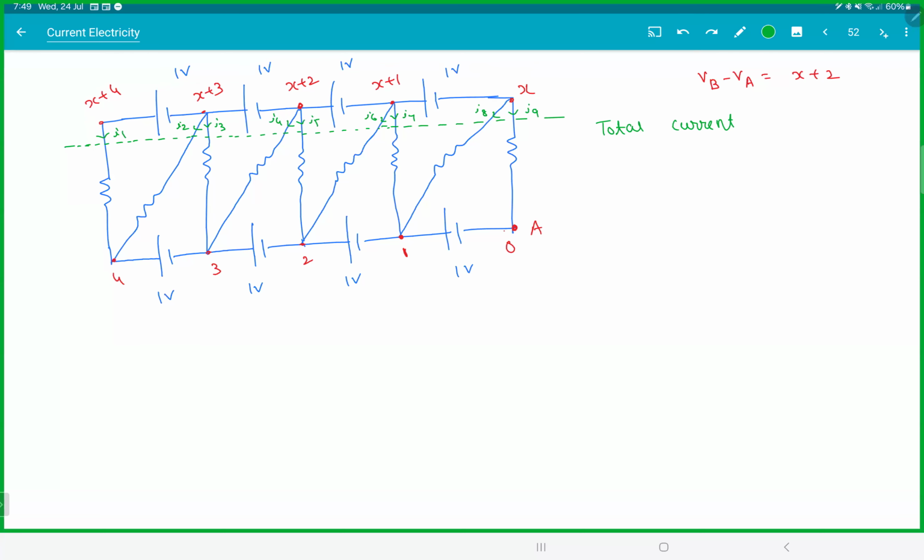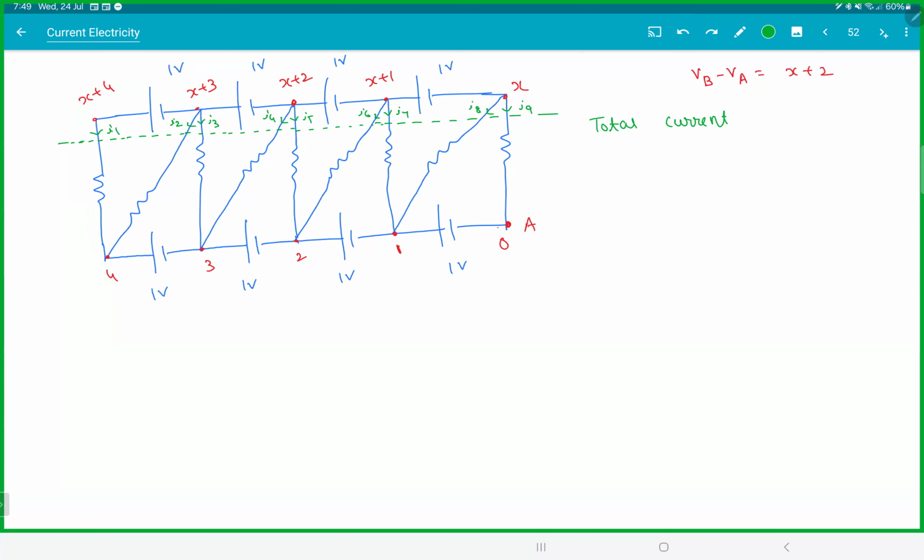Meaning, the current is just going in one direction. Remember, the current starts from it, it has to come back again. If the current starts from a battery, shouldn't it come back to the battery? Or you can say current passing through all these nodes, the total sum should be 0. Some nodes are receiving current, some nodes are giving current. Total should be 0. Is that making sense?